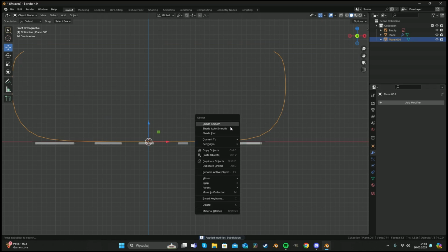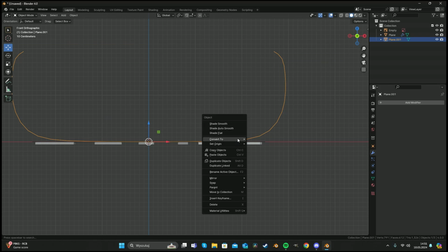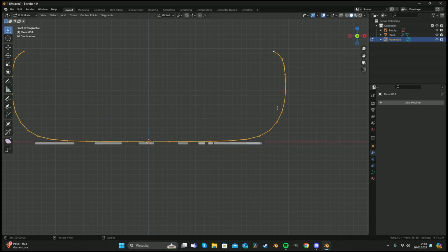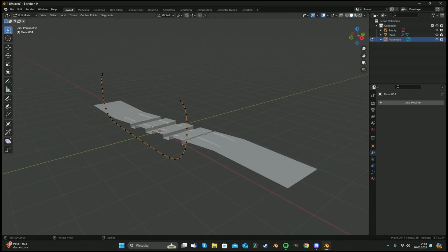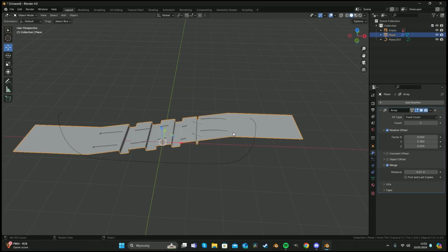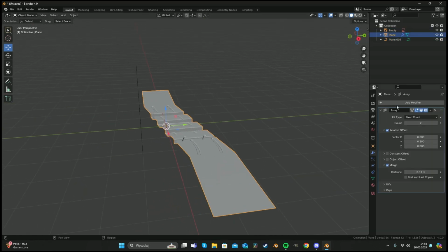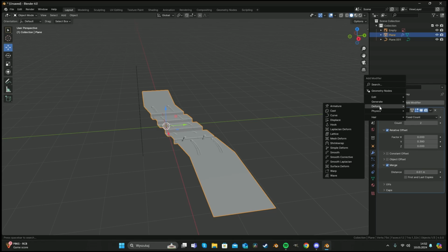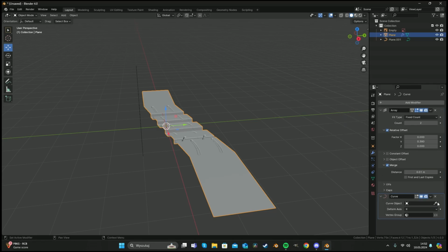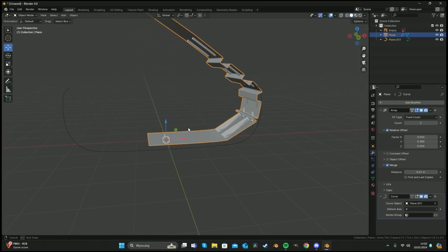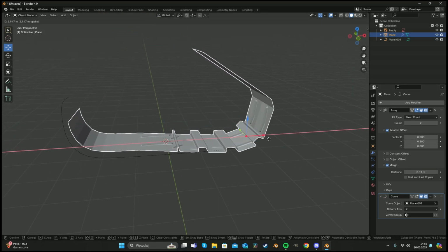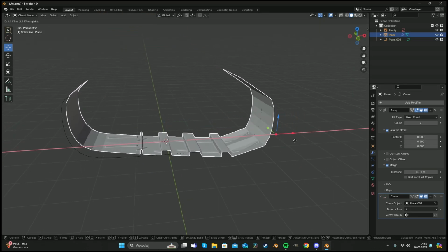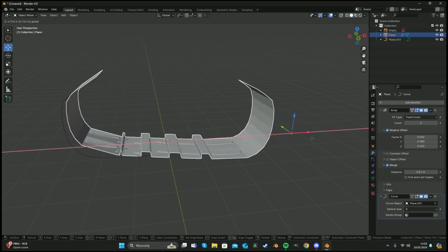Now we have converted into curve. So we're gonna press W, convert to curve. It's no longer mesh. And we're gonna select our thread, add modifier. Now time is for deform, and we're gonna select the curve. Here we're gonna select our curve and just simply move our thread,